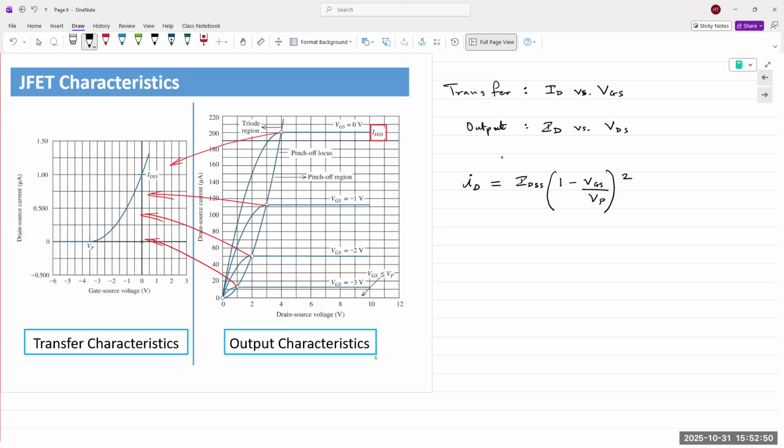In the lab, some student groups had about 1.6 volts as their pinch-off voltage, and some groups had about 2.5. There was no in between. But still, according to the manufacturer themselves, there's a wide range of variation.